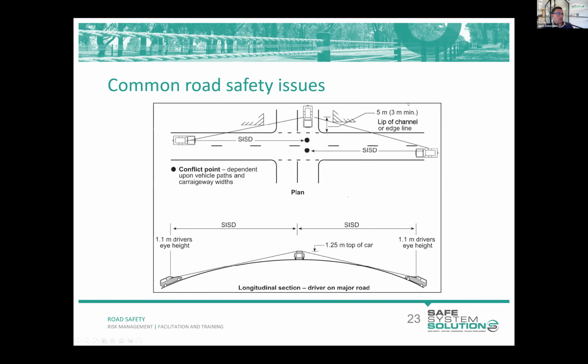Another thing that I'll point out here is that it's important whenever we are looking to the Austroads guides that we also consult the jurisdictional supplement to the guide if there is one. One little thing that stands out to me here is that the Austroads Guide nominates a setback distance that we had to measure our site distance from. The Victorian supplement for one says something a little bit different to this. So always consult your jurisdictional supplement, which does take precedence over the Austroads guidance.